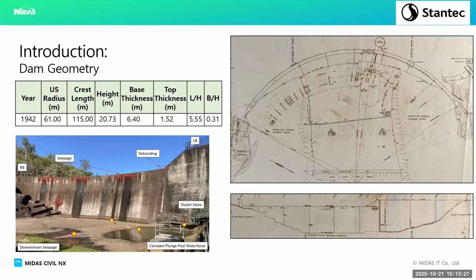We observe the structure, and there are particular points that you look at here. You'll see, for example, on the one, there's seepage, some lime deposits. Now, when you observe that, before you go back, you can also say those lime deposits would affect the interface or the lift joint strength parameters in terms of friction and cohesion, and you can actually spot that across the entire dam face, and you can see spots are more concentrated than others.